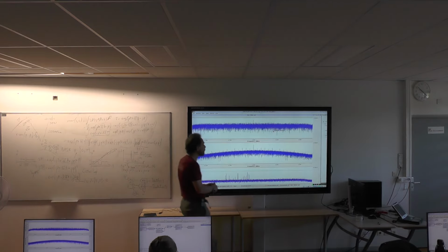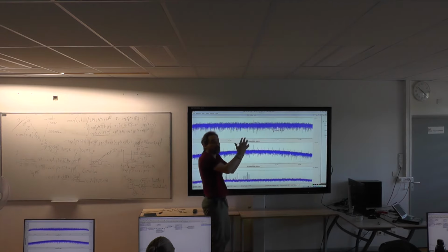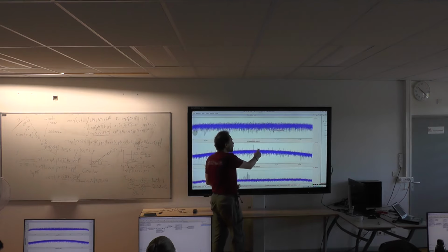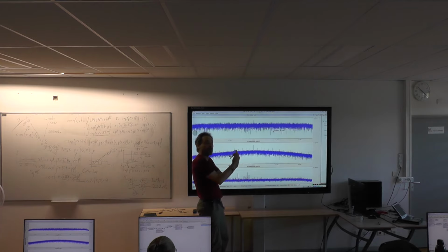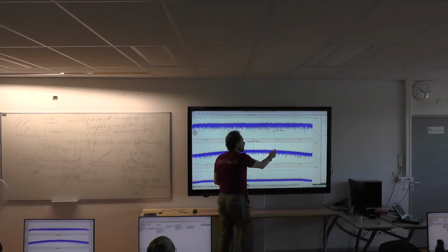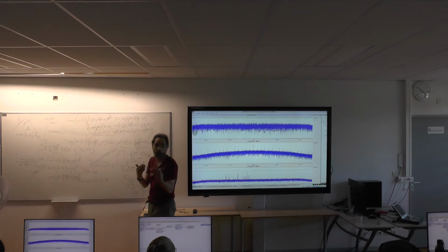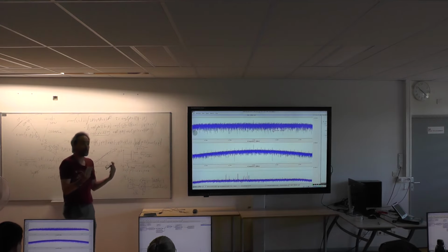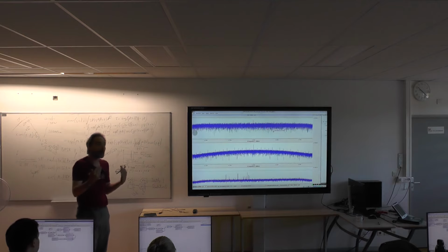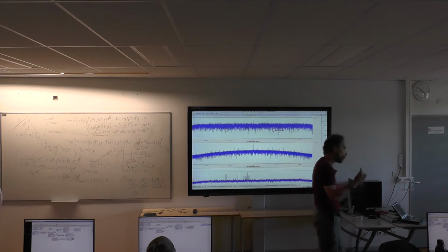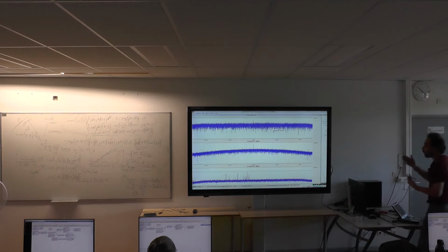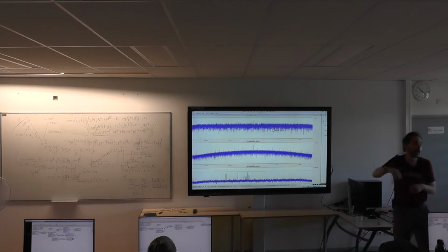So what you see here is, zero delay, I'm looking at myself, autocorrelation, GPS, GPS, GPS, and this is GPS plus Galileo. But they overlap because Galileo is exactly 4 milliseconds and GPS is 1 millisecond. Then GPS, GPS, GPS, GPS plus Galileo. So actually you cannot separate the various constellations, because all the constellations broadcasting in the L1 band are multiples of 1 millisecond code repetitions. So whether you have Galileo, Beidou, or GPS, they all have autocorrelation peaks every 1 millisecond.